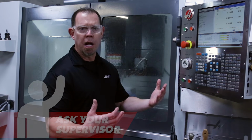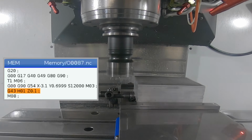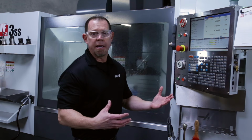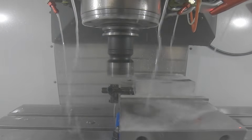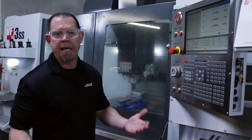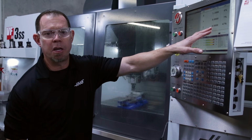Since I'm still in single block mode, my cutter finished moving down to the part and is right beside the workpiece waiting for the next command. But I can't see anything because the coolant came on due to this M08 command. Luckily, we have a way to override that command. I just press the coolant key here and it turns the coolant off. Now I can see my tool, and sure enough, it looks like it's the correct distance above the part based on this distance to go.